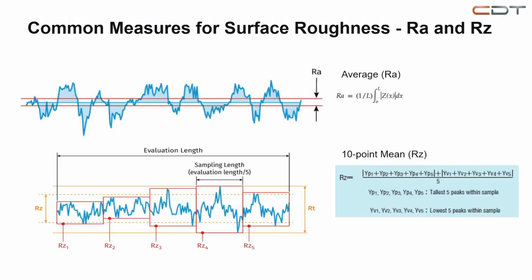But what is surface roughness? How is it calculated? How do we understand it? The most frequently specified roughness parameters are Ra and Rz. Ra means roughness average. It is typically used in the United States, while Rz, or mean roughness depth, is commonly used internationally. Ra is defined as the average variation of the roughness profile from the mean line. In mathematical terms, this is the integral of the absolute value of the roughness profile divided by the profile length. Because of this averaging, the Ra value is lower than the actual height of the roughness variations.